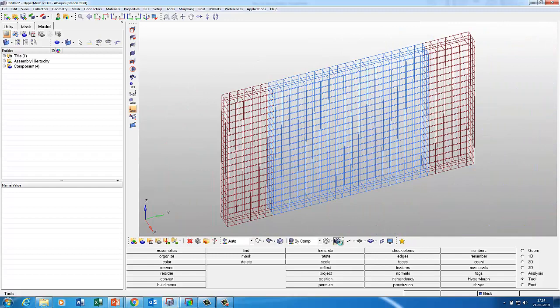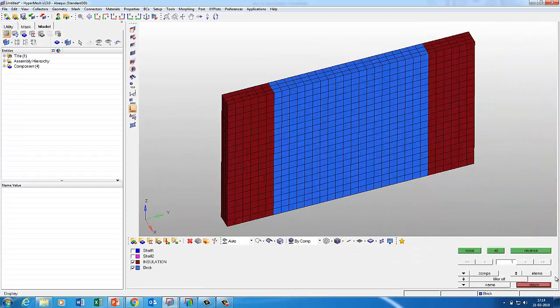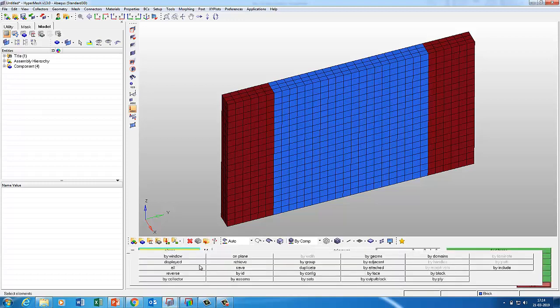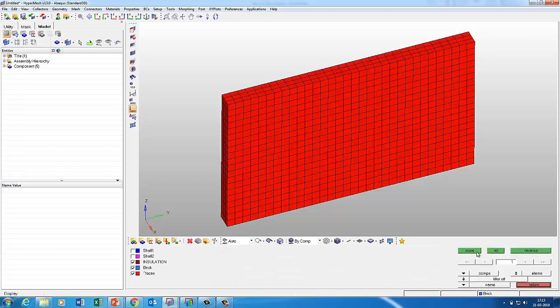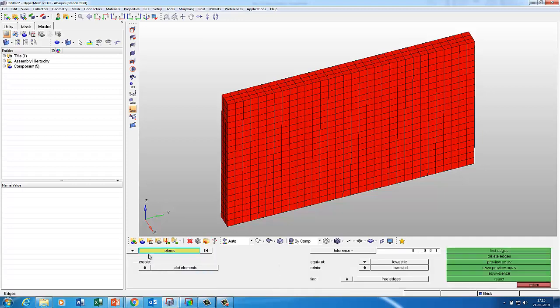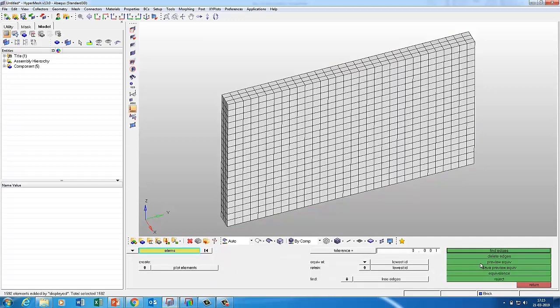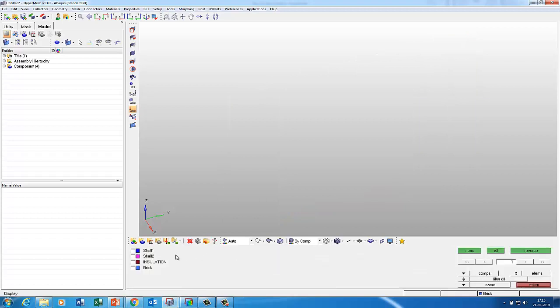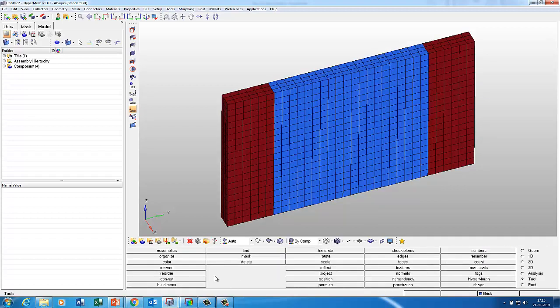Now another way to find whether everything is fine or not: you take all these solid components, go to the tool, you say faces, and you select all the element display and find face, and then you go to these faces and you may put Shift F3 and say element display and preview equivalence. You should get, find edge, you should get this message, no edges are found. And if you put T section, you say find edge, no T section found. So everything is fine.